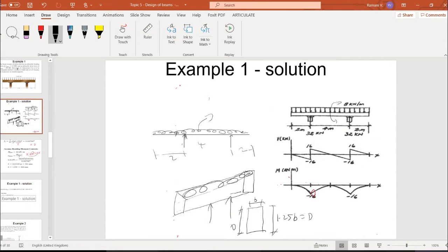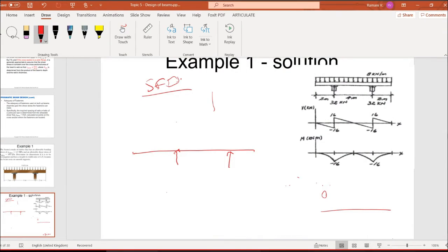Okay. Now let's solve this question with a free end. If I put it like this, it's not showing a free end. I just put it right. In this case, if it is a straight line, just UDL is acting, right? UDL is acting and the supports are at the ends. Normally what you do, you convert into span, right? If this span is L meter, automatically you convert this into a point load by multiplying.